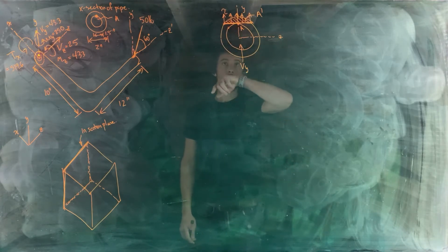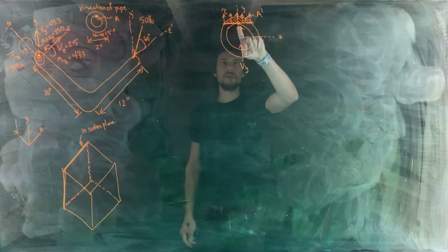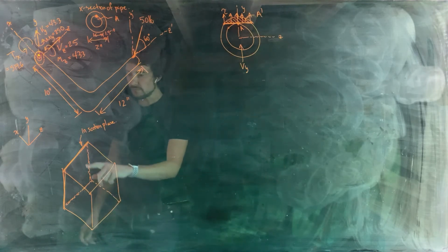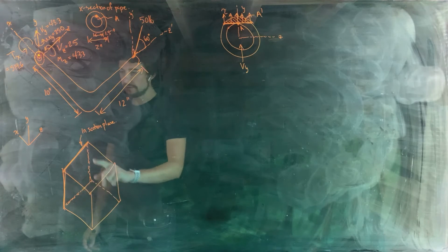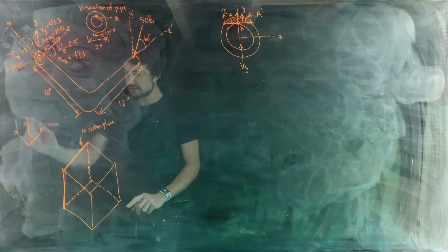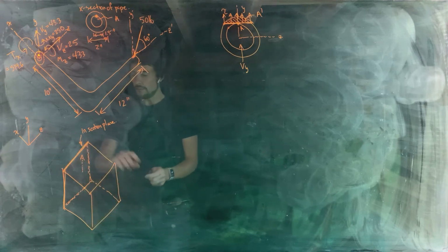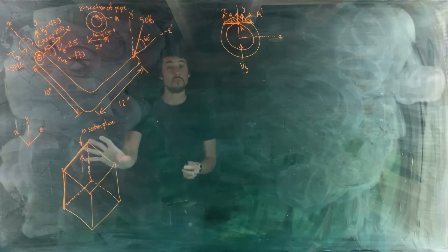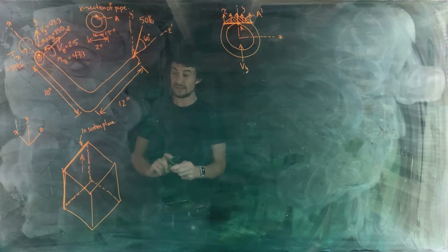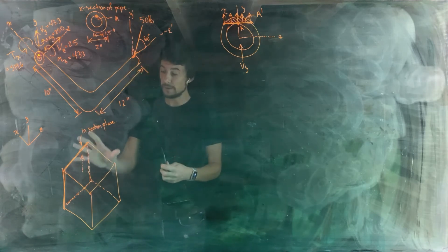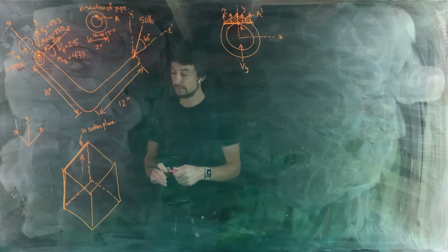So what you want to do here is place a shear stress in the positive y direction. Go to the face of your element that's in the section plane and place a shear stress in the positive y direction. So this is upwards like this. Now before you make a mess of your notes, just watch what happens in this case with this shear stress. This is something that you wouldn't think about until you saw it for the first time.